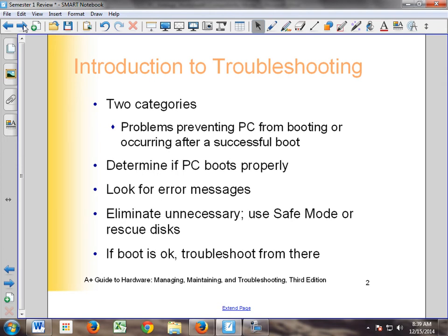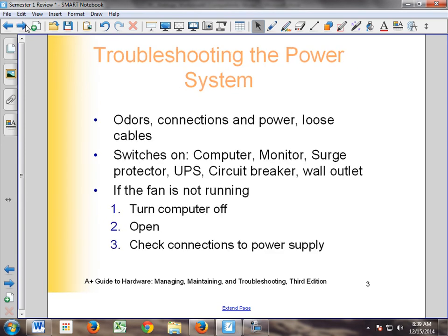Our second indication of a power supply going bad is our computer not booting or shutting down, because usually it shuts down from overheating, and that's a normal thing that happens with the power supply. It runs for a while, then shuts itself down. So the first indication is usually lack of airflow from the fan, unless it's way over wattage, and then it just runs for a little while and shuts down when it overheats, even if the fan is running.